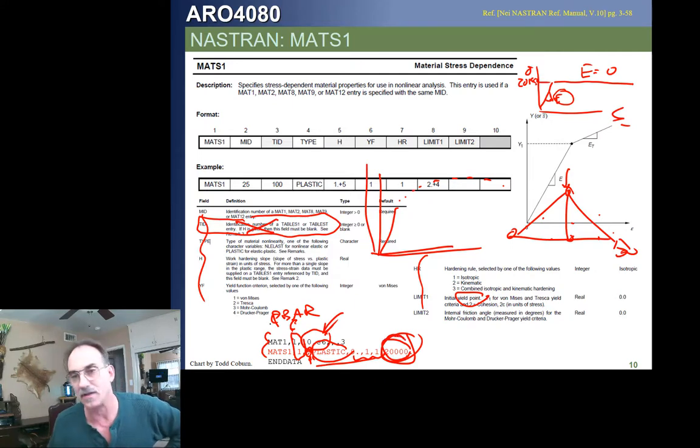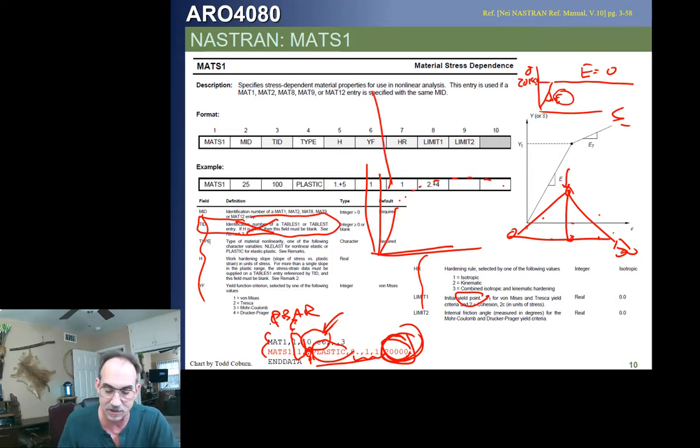In this case, it's 20,000. On the last slide, it was 50,000. So at 20,000, from then on, that rod or bar will continue to hold whatever load it had before, but it won't add any more load to that. And it basically will go as if it buckled, or as if it just kept on yielding and yielding, like we see when the stress-strain curve gets totally flat.